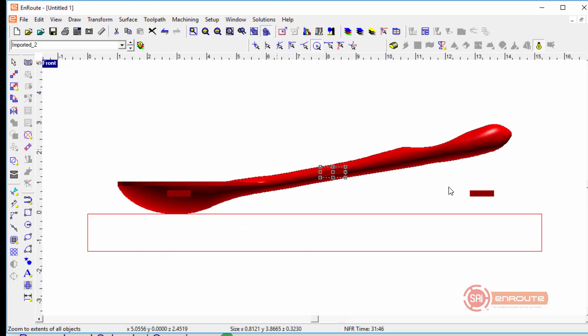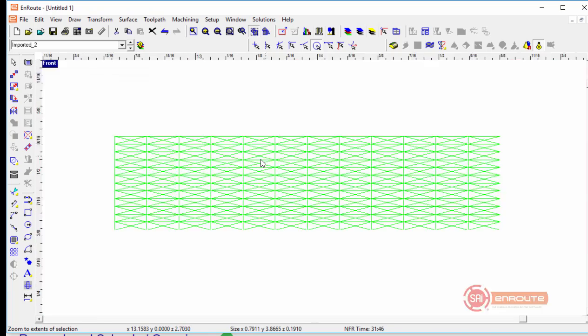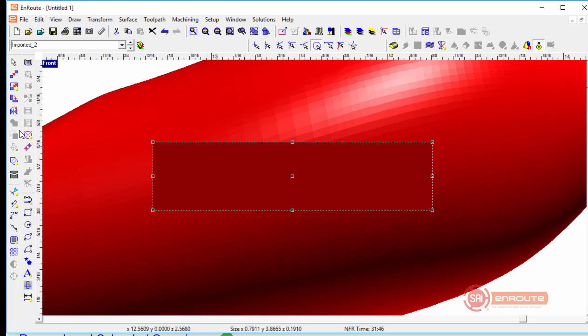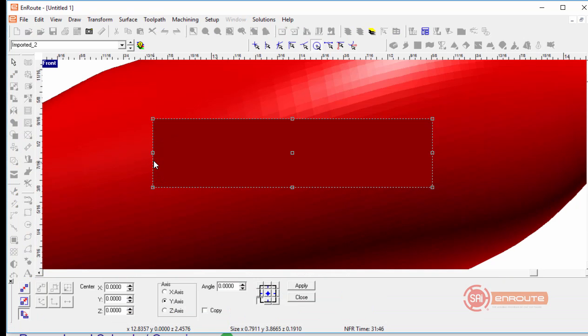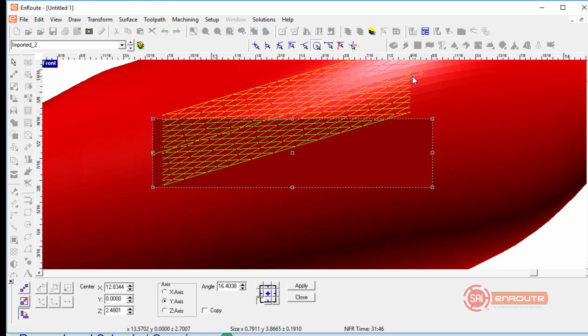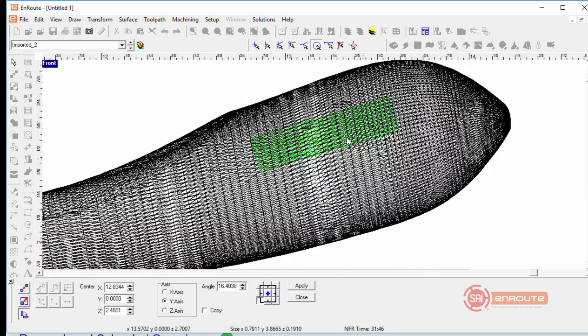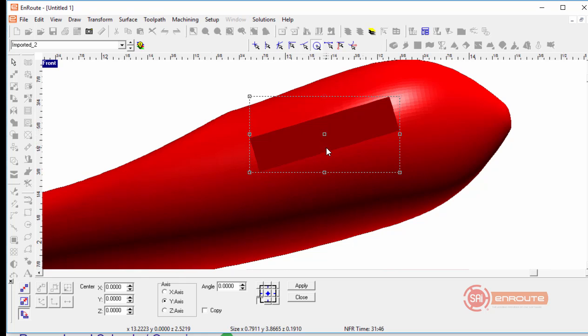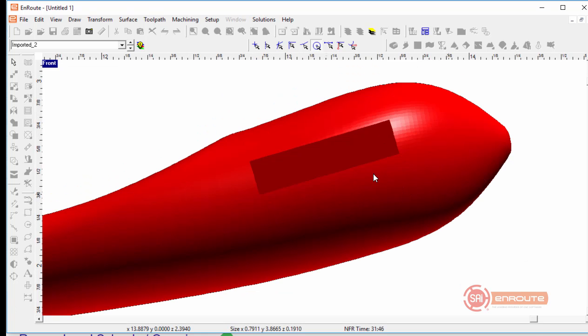All right, let's go back to view the whole part now. Let's go here to the side view, and I'm holding my shift key down to keep it from moving much in the X or Y. Then I'll use my zoom to zoom in on it here, back out a little, and once again we're going to click the two sides here and then try to align it so I think it's going to look good relative to the angle of the part there.